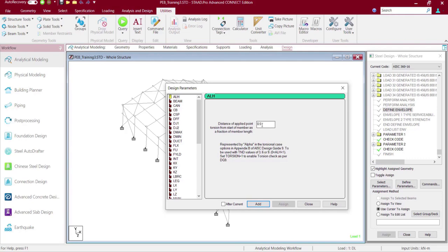Now, basically, what happens? The designer first takes a plate and then they see the drawing and accordingly they carve out the flanges and the webs, stiffeners and so on and cut them out of the plate, and then according to the drawing and geometry they will assemble them, fabricate them, weld them together to give it the final shape. Say for example the web tapered sections.